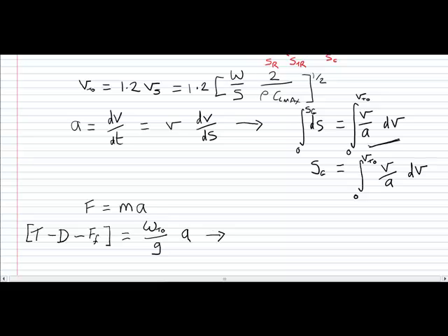Now, just to reiterate, this value here, thrust, may or may not be a function of forward speed. Drag certainly will be, even if you've got a constant drag coefficient. The absolute value of drag, which is what this D represents here, will be at least a function of V squared. And you've got a rolling resistance, which, as we'll look at in a moment, will normally also be a function of the aircraft's forward speed as it rolls down the runway.